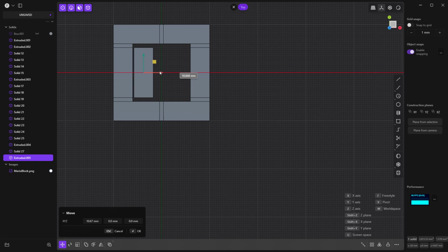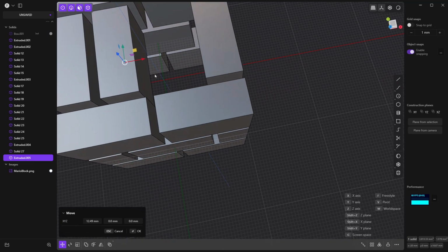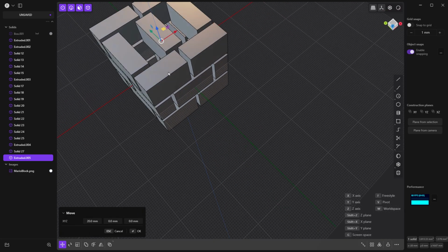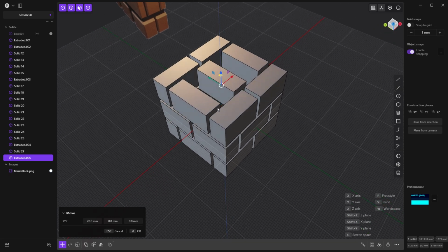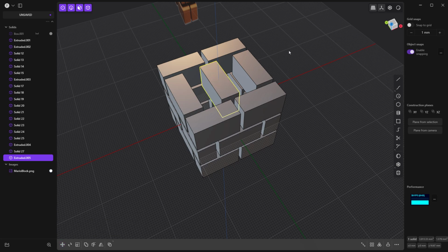So I'm going to move it to a position. Actually, let's go ahead and move it to the center. So let's rotate this around. And as we begin moving it, click X, hold down Control, snap, and it'll snap it to that origin position. The block itself is pretty tall. It's okay, I don't really care in this instance, but I'm going to right click to accept.